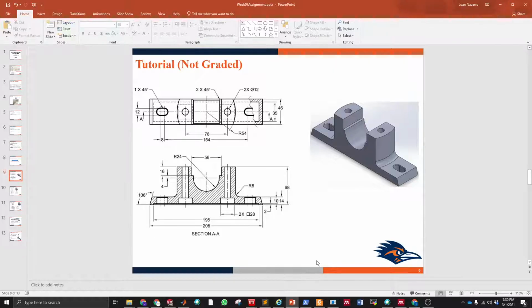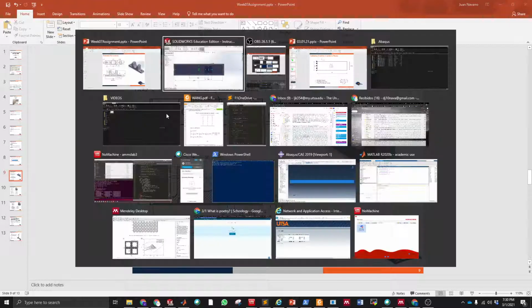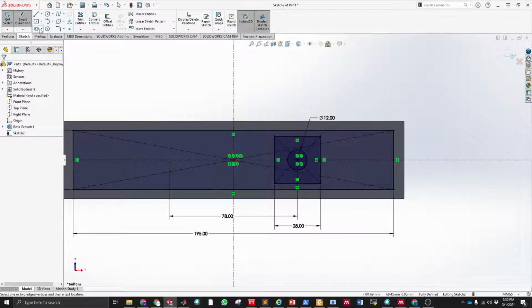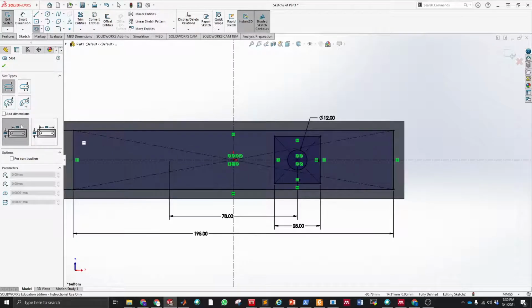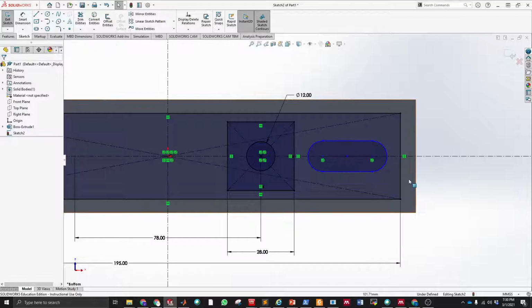And finally, we have this oval shape here and here. We can find those here. It's called the straight slot. We have two arcs joined with these two straight lines. So I'm gonna do first one center of arc, then the second center of the arc, and then the radius of those arcs.